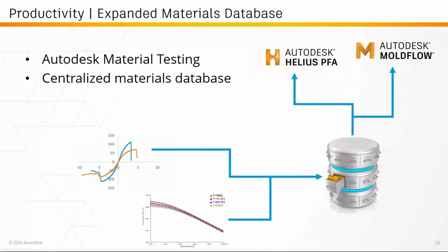As far as productivity is concerned for the plastics workflow within Helius PFA, we are significantly expanding our materials database and also including nonlinear mechanical testing for unfilled and fiber reinforced materials. So now Autodesk can test your materials and we can include them in the MoldFlow database. What that means is the users can run the MoldFlow simulation and all of the nonlinear mechanical data will automatically be transferred over to Autodesk Helius PFA.